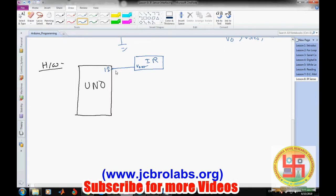In order to visualize it, we have used the previous circuit, which was the DC motor. Our DC motor is connected to pin number 9 and pin number 10, and there is a driver IC which we discussed in our previous video. This is the L293D, and then we have a DC motor here. This is going to pin number 2, this to pin number 7, this to pin number 3, and this to pin number 6, and all other connections we have already discussed in our previous video. And there is one more LED here.